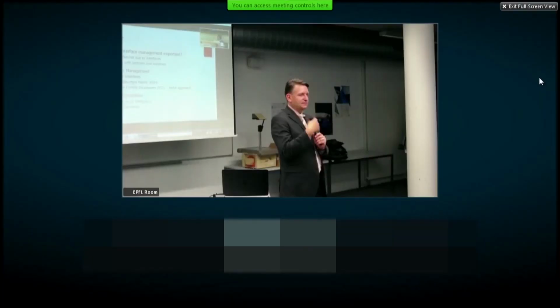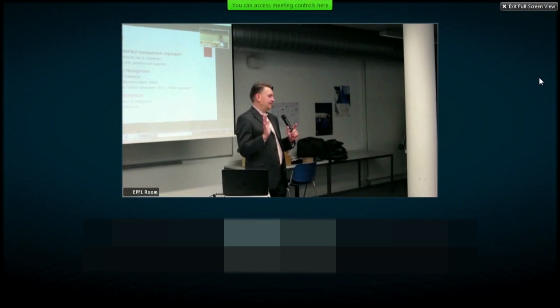This is a really, really big deal in practice. For example, if you modify the interface because you think it's better for you, and it's different from the ICD, and then there's a failure in your system, and you blame the supplier and say, your box failed, my mission got screwed up because of your box, and then it turns out you actually implemented an interface that's in conflict with the ICD, the supplier will step back and say, that's not my problem. You didn't follow the interface definition, and just changing one pin or one polarity can lead to a system failure, right? So you have to pay a lot of attention to the details here.